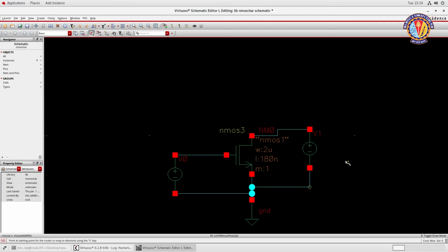By default, the transistors will have a width of 2 microns. But our entire experimentation will have a fixed value of 400 nano. If it has been mentioned to use a different value, you can proceed and use it, or else it is better to maintain the width of the transistor as 400 nano.